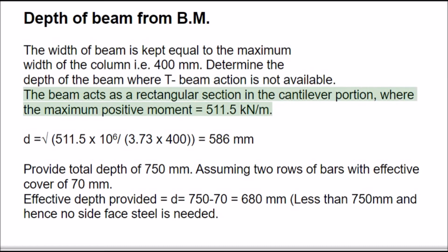The beam acts as a rectangular section in the cantilever portion, where the maximum positive moment equals 511.5 kN.m. d equals 586 millimeters.